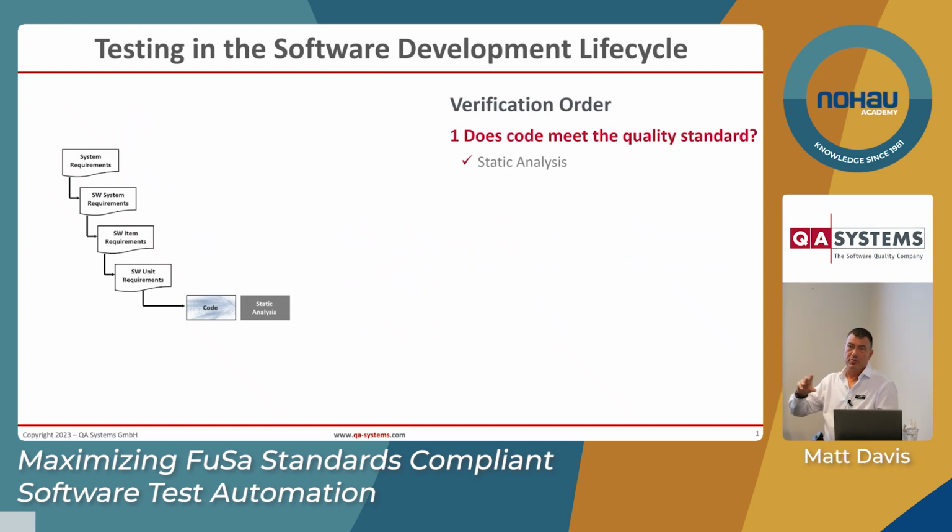Static analysis should be done initially before you do dynamic testing. Why? Because if you change your code to meet a coding standard compliance or to understand or fix a perceived runtime error found by static analysis, you don't want to rework your code and your tests after you have done that analysis. So do static analysis first and then do it all again at the end.